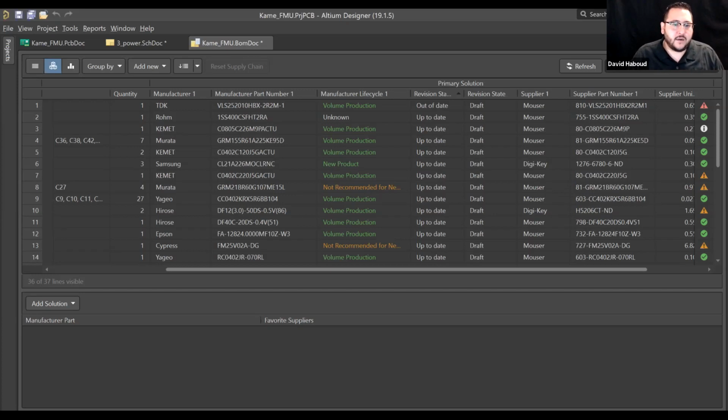So we come back to Altium Designer. We have the design here in 3D, view changes. It starts detecting the changes and processing the board data, and I'm able to click on it, and it will show me the movement that has been processed, and I am able to select the changes and apply the changes. You see here some grayed out information. That grayed out information pertains to things such as plated through holes that exist in the environment inside Altium Designer that don't have a good way to be modeled within SolidWorks.